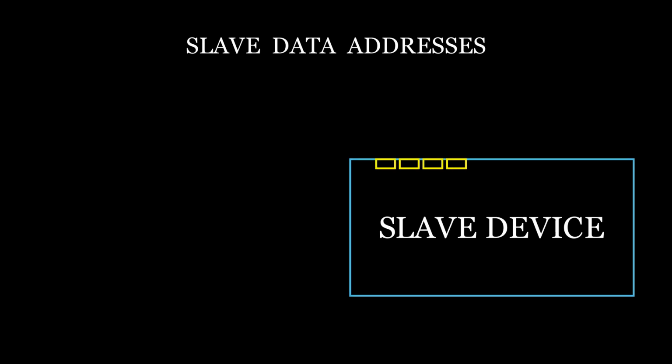The Modbus master might read data from devices with digital inputs. These inputs detect whether the connected line has a voltage above a certain threshold. For instance, on a 24-volt DC line, the input senses if the voltage exceeds 14 volts DC. This example is typical for PLCs and other industrial automation devices.